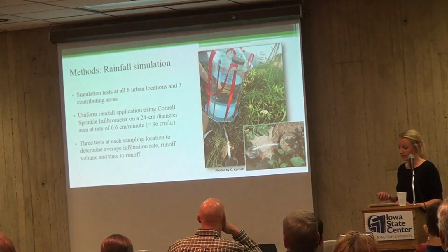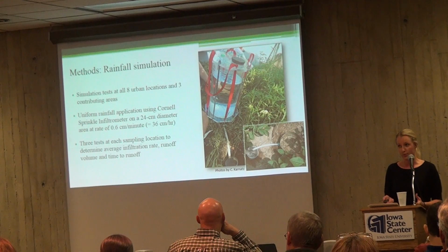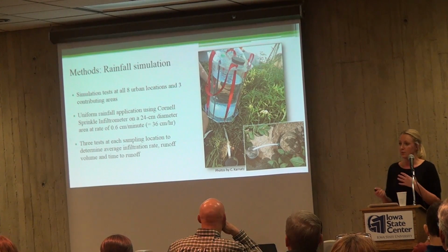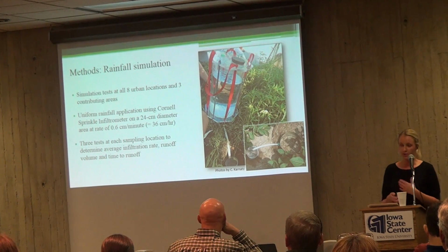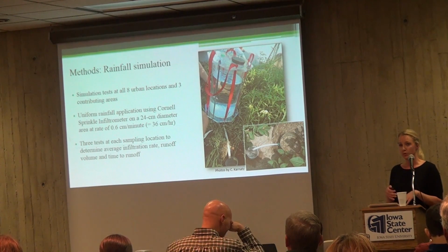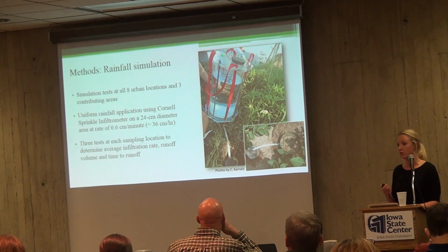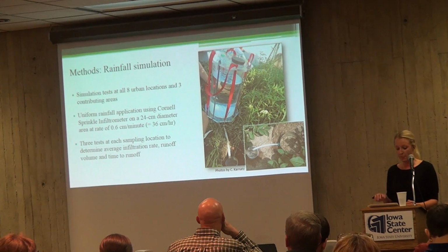Moving into our methods of assessing these practices, we first looked at infiltration as a performance parameter. The velocity at which water enters the soil profile is known as the soil infiltration rate, and it's an indicator of the soil's ability to allow water to move through the soil's pore space. Soil water infiltration and storage are necessary for root uptake, plant growth, and organism habitat.